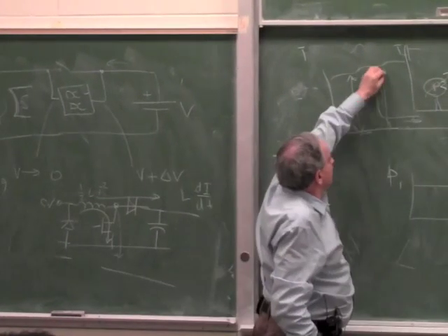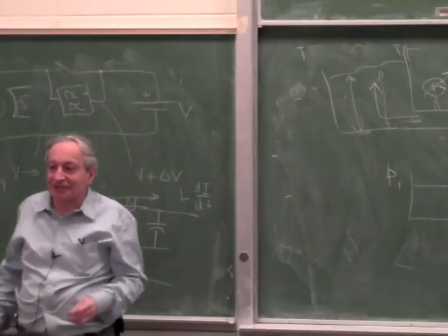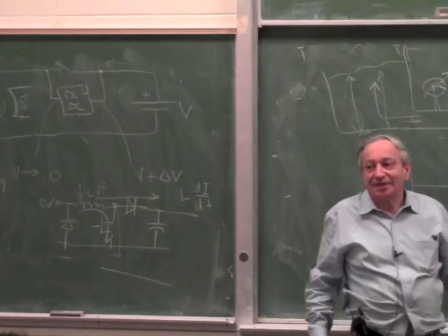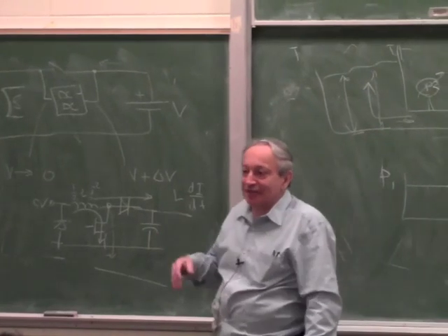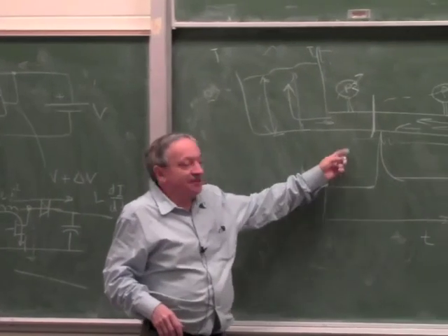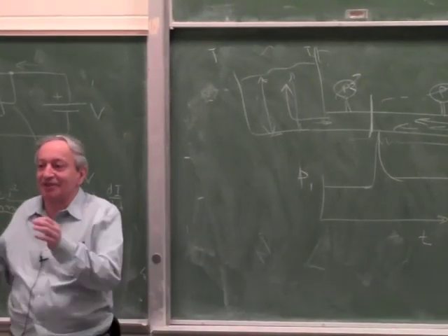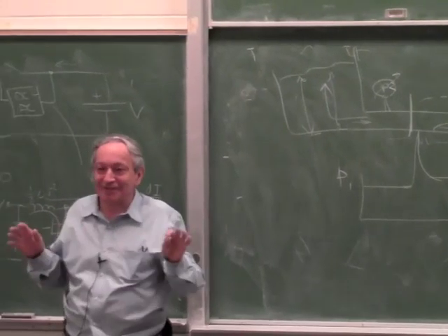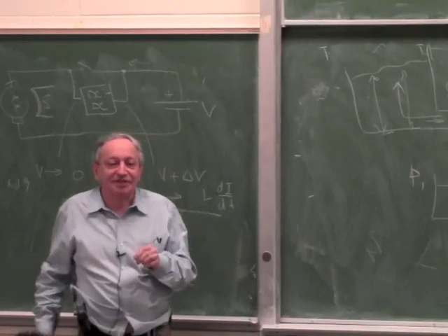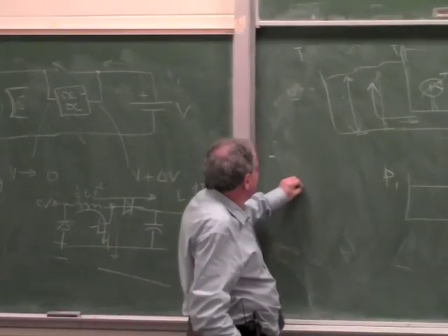The static pressure here is basically a voltage. It's like a back EMF in this case. And the curves of the hydraulic motors and pumps are exactly the same as the curves of electric motors. Except in here it's all DC. There is no AC fluidic systems. AC meaning the fluid goes back and forth. It doesn't exist. The nearest thing to an AC fluidic system is something they do in hydraulic servos called dither.